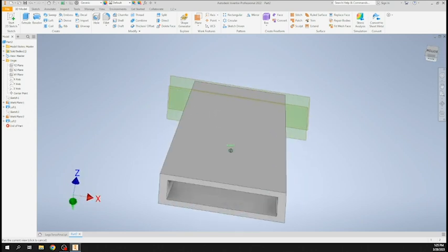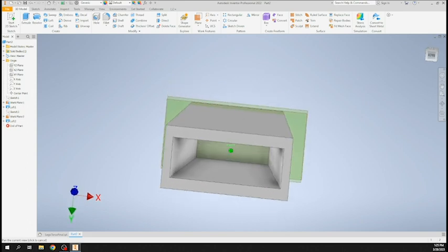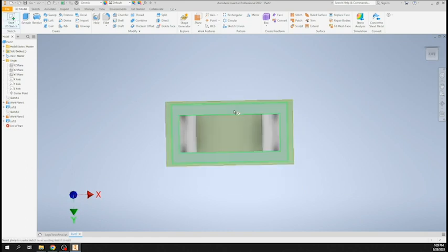Now, before we go on to the head and the arms, I want to deal with some internal features here. If you ever look at the bottom of a Lego, you'll see there's some things going on in here. So let's take care of that first. We're going to start a 2D sketch right on this outer surface at the bottom. So go ahead and click on that.